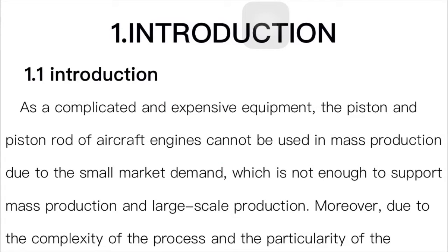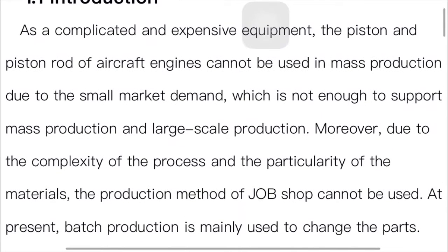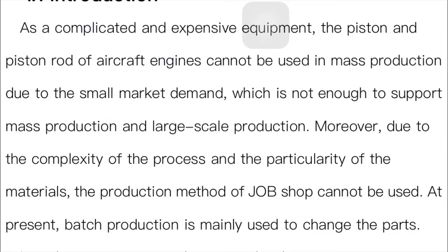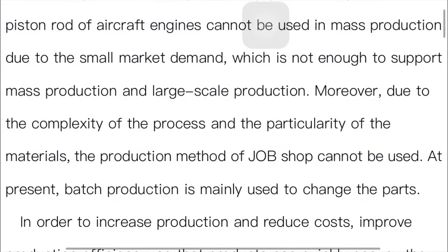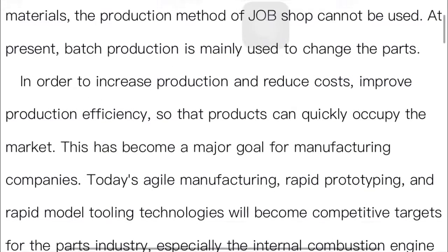As complicated and expensive equipment, the piston and piston rod of aircraft engine cannot be used in mass production due to the small market demand, which is not enough to support large scale production. Moreover, due to the complexity of this process and the particularity of the materials, the production method of job shop cannot be used. At present, batch production is mainly used. That is the assumption on the type of manufacturing system.